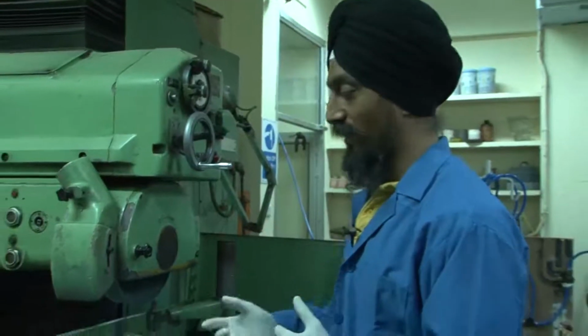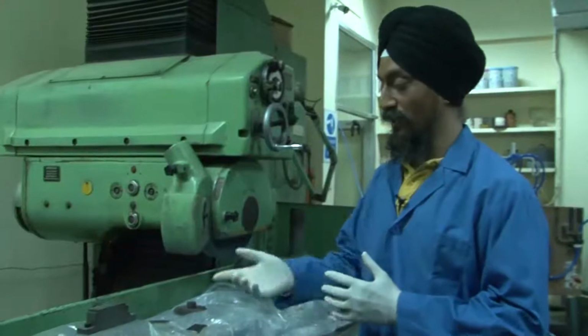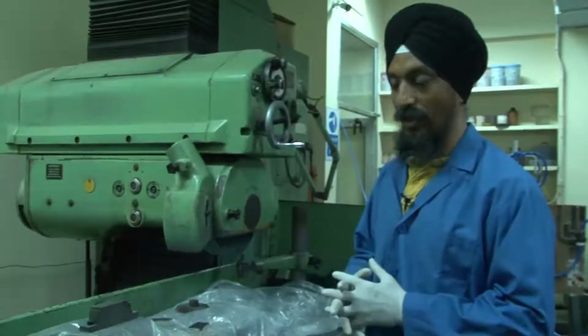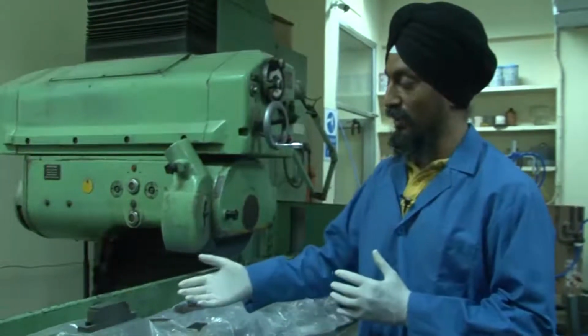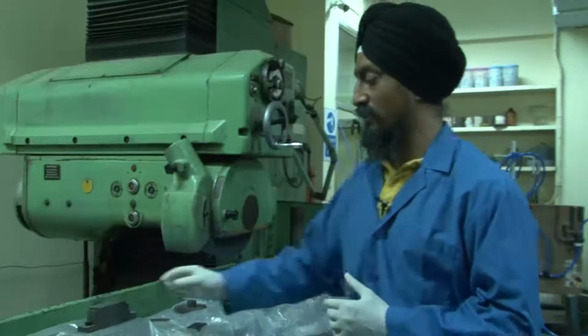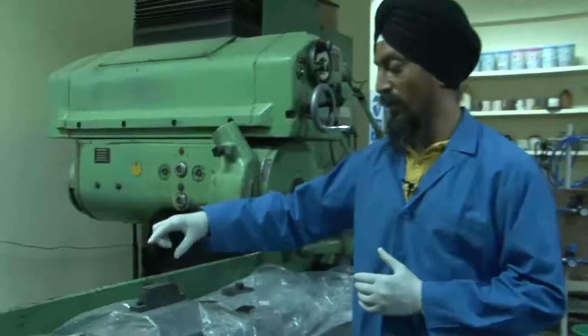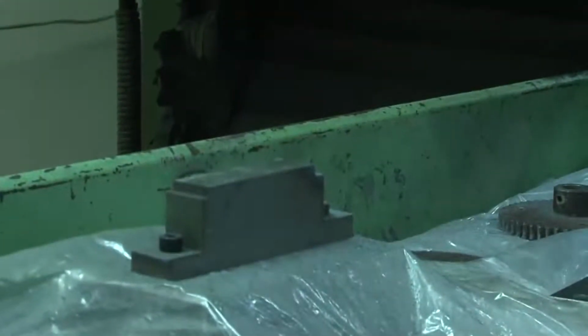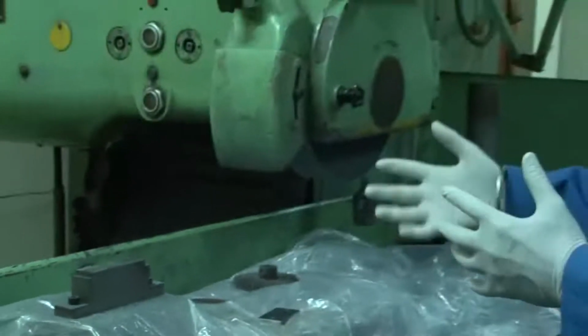We are here in the Manufacturing Science Lab of IIT Kanpur, India. Here we have a setup in which we'll do grinding on a titanium workpiece. We have already given the details of the workpiece specifications, wheel specifications, and other things. This workpiece has 25 mm width and 160 mm length. It will be machined with this aluminum abrasive wheel.